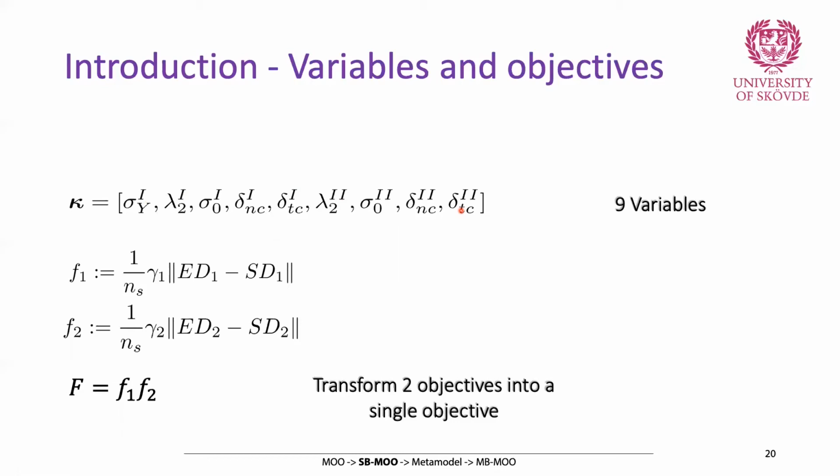We can run physical experiments on adhesives and draw the stress strain curve. So by performing experiments and drawing the stress strain curve, you have an accurate stress strain curve which is based on physical experiments. Then you can run simulations, finite element simulations, and find the same stress strain curve.